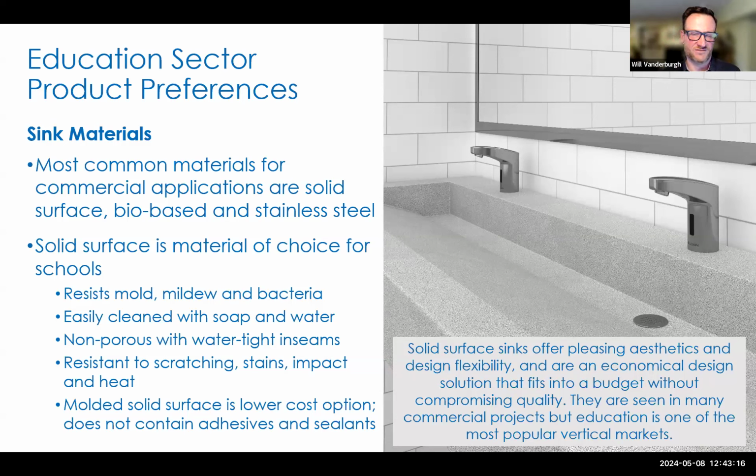You see those in a lot of those multi-station lavatories that we touched on. The other neat thing about it is, like I mentioned, it's repairable. If vitreous china is damaged, then you're replacing the entire fixture, whereas some of these molded solid surface technologies, if a student chips or damages it, you're actually able to repair it on site to a near flawless finish, which returns it to its original condition.